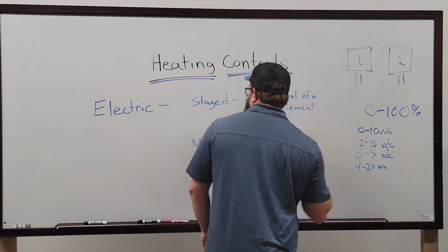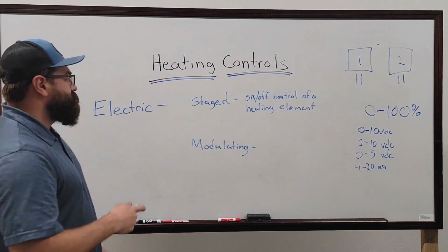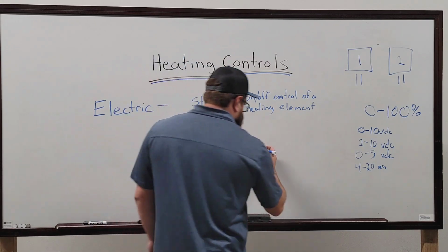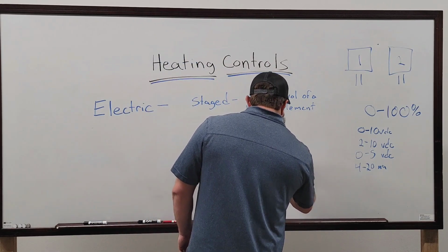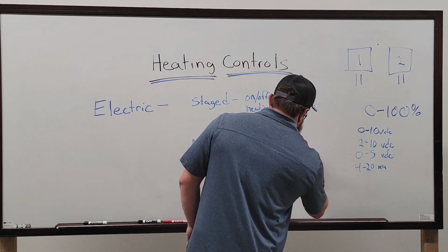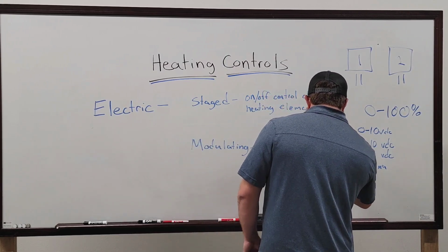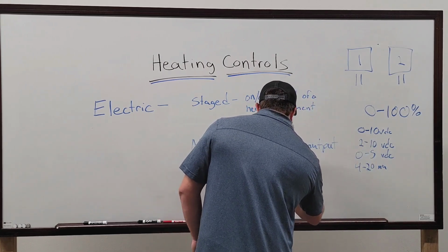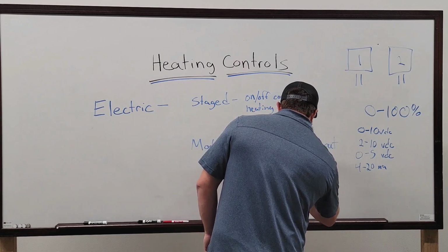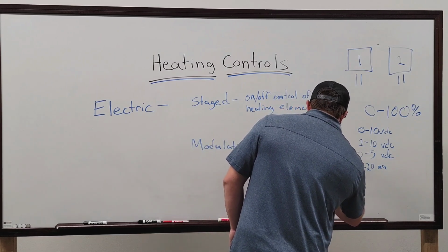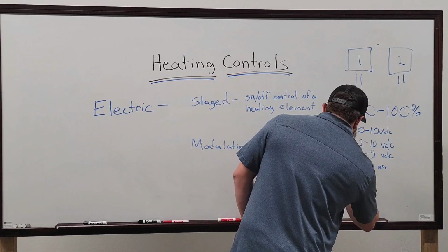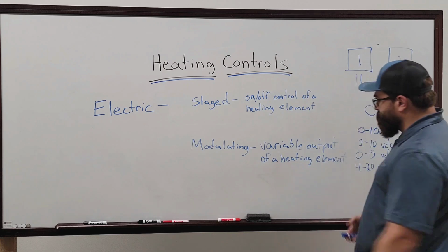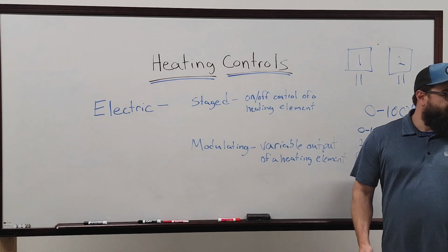Sorry for my handwriting. All right, back to the electrical. So staged is an on-off control of a heating element. Modulating is a variable output, so that'd be like an SCR. So modulating is a variable output of a heating element.